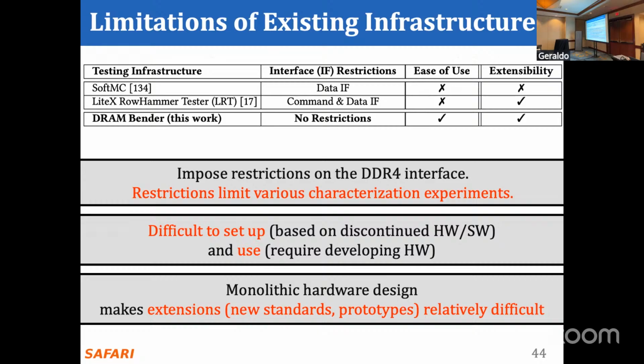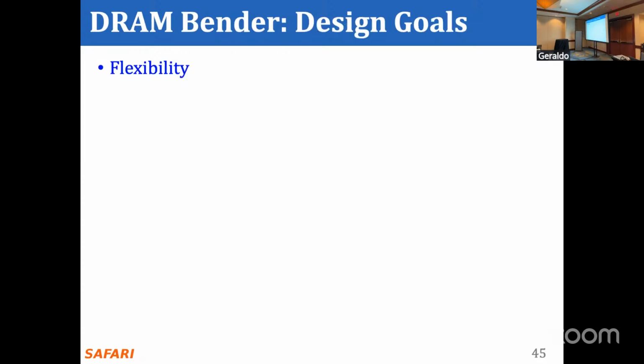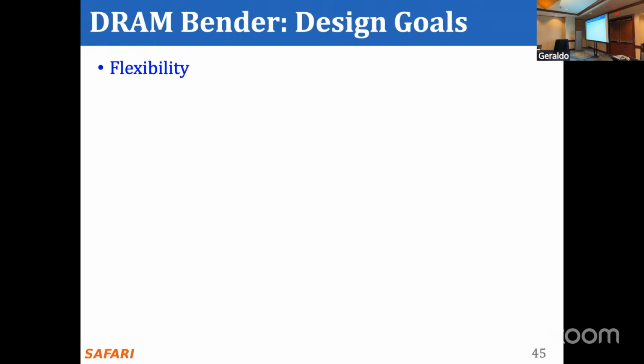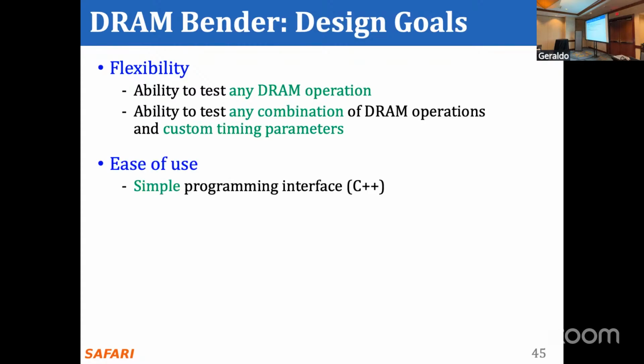SoftMC, for example, was very difficult to get running at that point in time because of legacy software and hardware requirements. Yes, Geraldo's signing me that I have 5 minutes left. Okay, and they had extensibility issues whereby monolithic hardware design prevented users from easily modifying code to add some new features. And our goal with DRAM vendor was to basically get a superior DRAM testing infrastructure developed. And these were our key design goals.